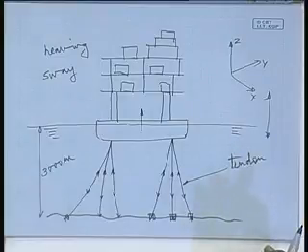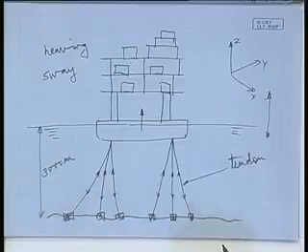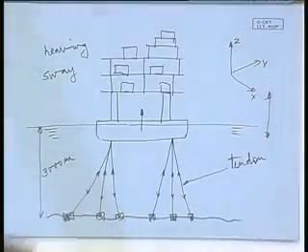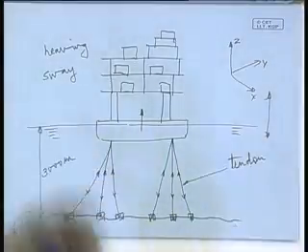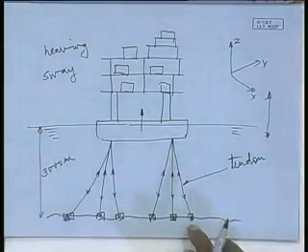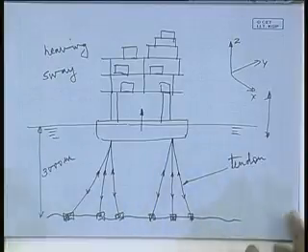So here the biggest challenge is fixing the bottom seabed connections. Making the seabed connections is the major challenge, because the other things have become very easy. It's just like a ship kind of a thing, a floating thing, and over that it's all steel structure, decks fitted with necessary equipment. So the biggest challenge is actually connecting the bottom, those so-called clamps or fixtures wherein you are going to clamp the tendons. So that is what is TLP.